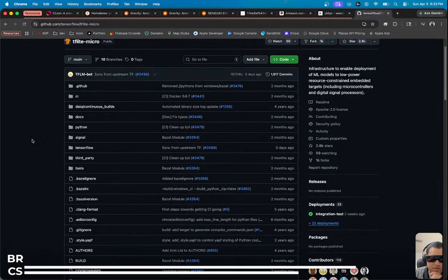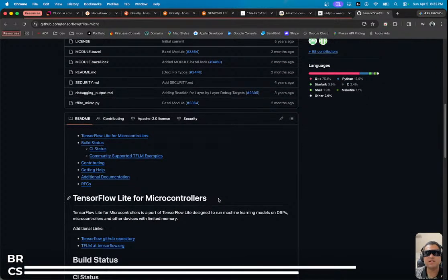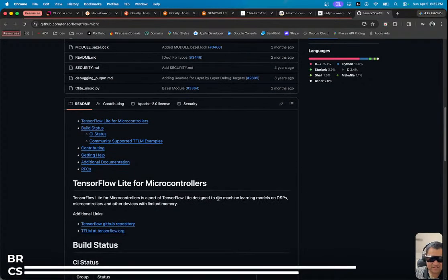Tensorflow Lite Micro. Okay, Micro. That is what we're going to shove into the ESP32 to ingest the numbers, and then tell us, did we do this? Did we do this? Because if we can get a model that runs on ESP32 through unfiltered data, then that's a lot easier, because then you're just gathering movements and retraining the model, and then you can expose the result of the model rather than writing complex algorithm.